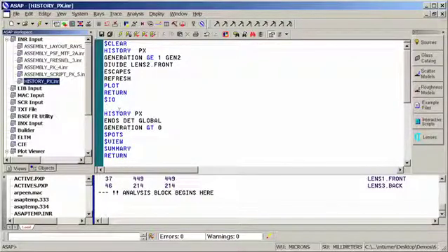In this particular case, what I want to do is look at all of the rays that make it to the detector, and also get an idea of where all of the rays that didn't make it to the detector, at what surface within my design they exited out of the system. This is an example of Path Explorer commands within ASAP. This first set of commands is for the previous example where we looked at the Fresnel reflections off the front surface of the second optical component.